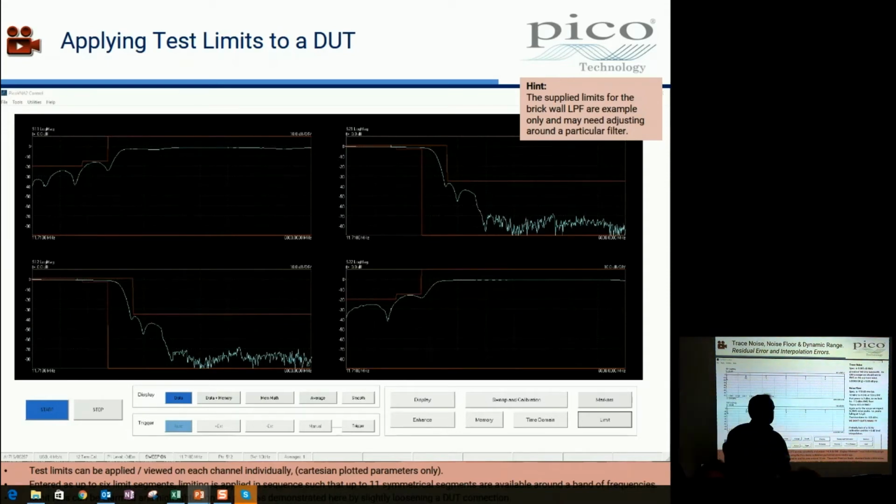Oh yes, and just a reminder here, this noise floor, 118 dB RMS typical, that's in the bandwidth 1 megahertz to 4 gigahertz. We are allowed to go slightly out above 4 gigahertz, and it's at 10 hertz bandwidth. So you have to do this as a rather slow process, which we'll demonstrate. Port power is 3 dBm. In the case of the test I'm going to do here, port power is 3 dBm.